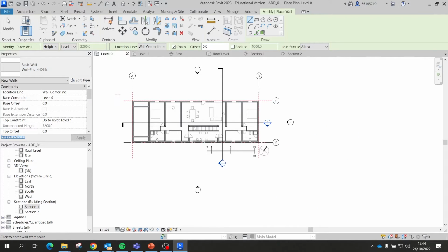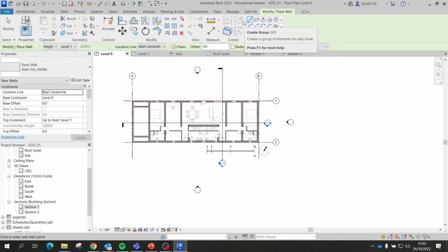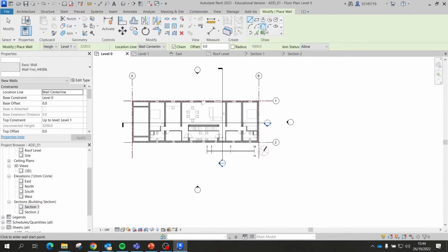When I draw a wall, I have multiple ways of drawing a wall. I can draw a line. I can draw a square, which is interesting, maybe something we might think of since we have the guidelines for the square, right, which is our grid. A polygon, a curve. I can pick lines, which is also very interesting.